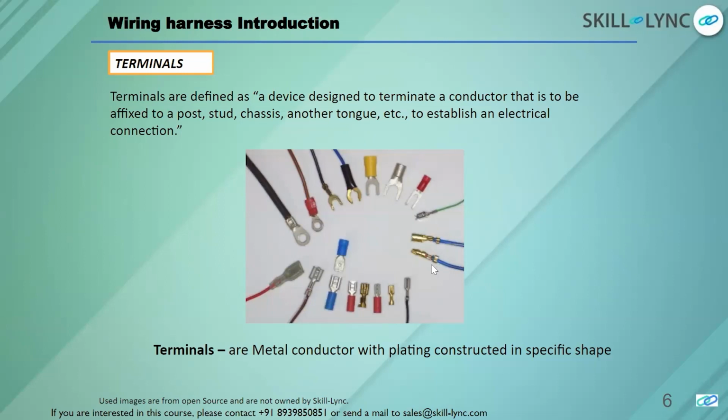These are again made out of metal. These components also, you can see the different color variations. Silver, gold. So what we do is the plating. The electroplating operation is being done, so that it can conduct the electricity without much resistance, correct? So electricity always tries to take the least resistant path, correct? So basically by using gold plating and all, we are actually having better conductivity, correct? So that's why you can see these kind of terminals being electroplated, correct? So this is what we generally do for terminals, right?